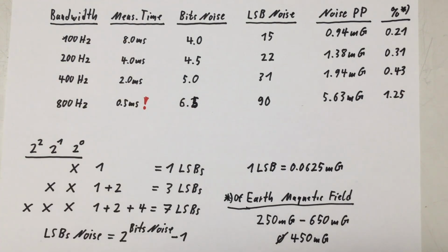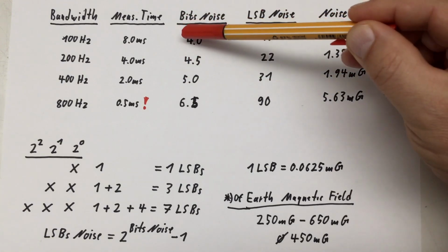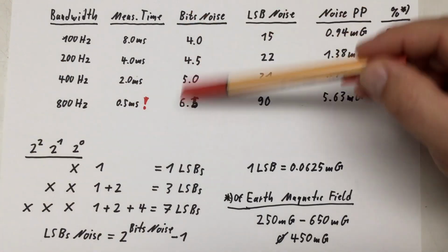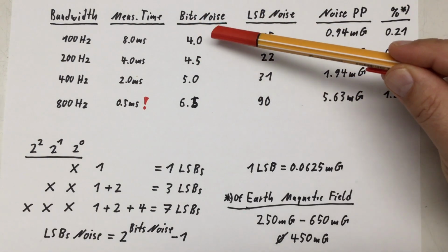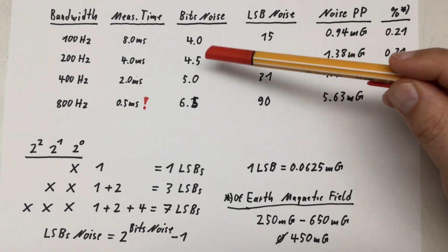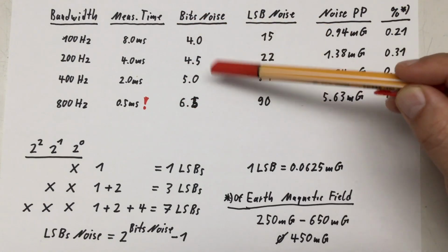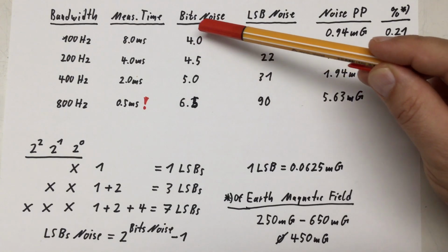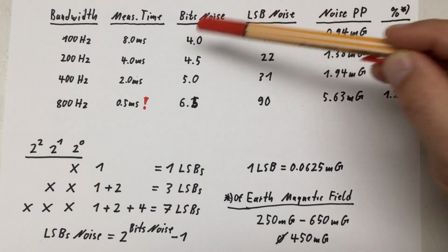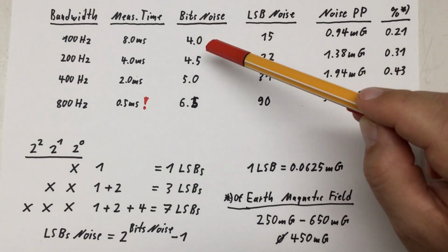Two remarks at that point. If you look at the bit noise numbers here, which start the lowest at 4 bits at the end of our 18-bit number being peak-to-peak noise, I have to revisit the question about going with the 18-bit numbers we can get out of the chip, probably cutting off 2 bits at the end, which are just noise, and going for the 16-bit numbers might, in the end, be the better option.